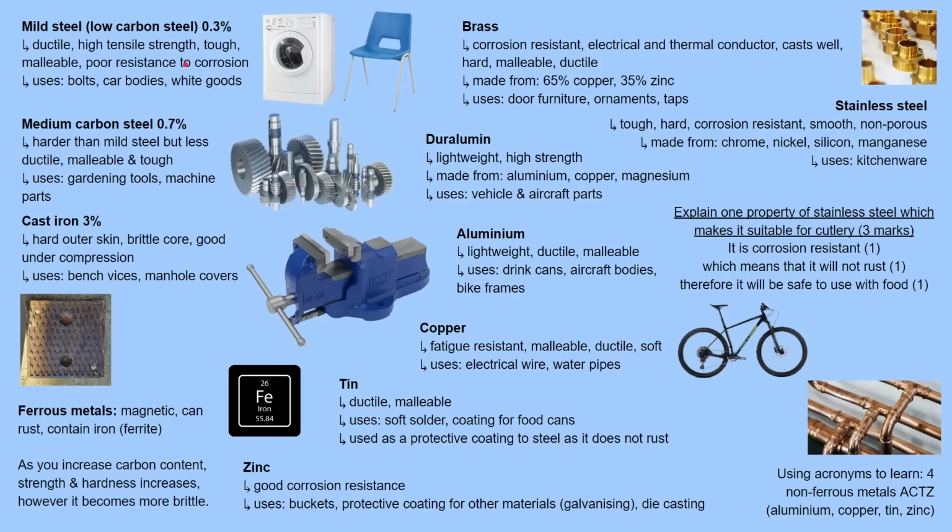Basically, iron mixed with carbon. So mild steel has approximately 0.3% carbon in it. It's also called low carbon steel. It's ductile, has a high tensile strength. It's tough. It's malleable, but it has a poor resistance to corrosion. It's used in bolts, car bodies, and white goods.